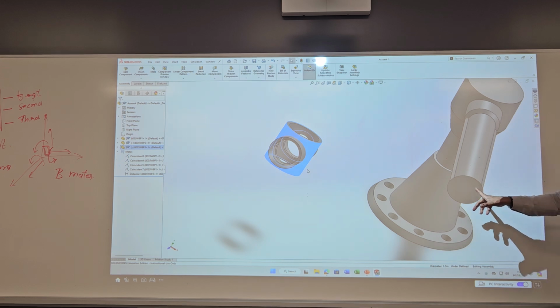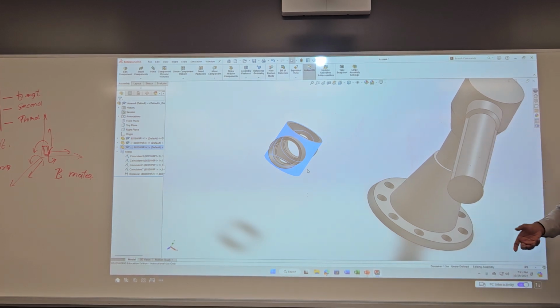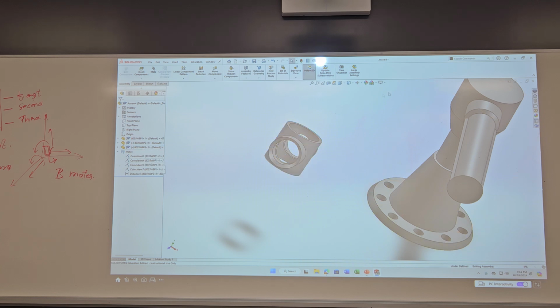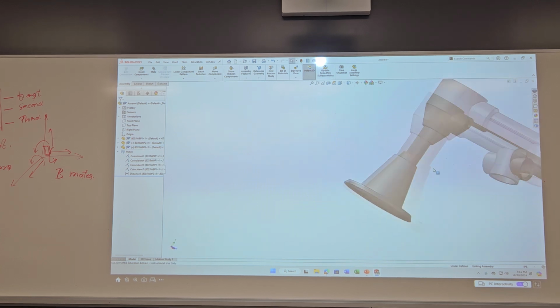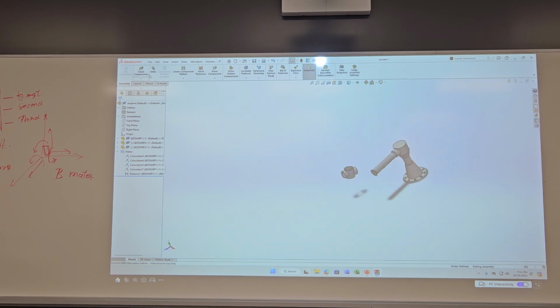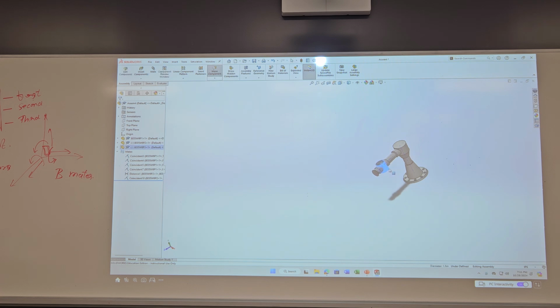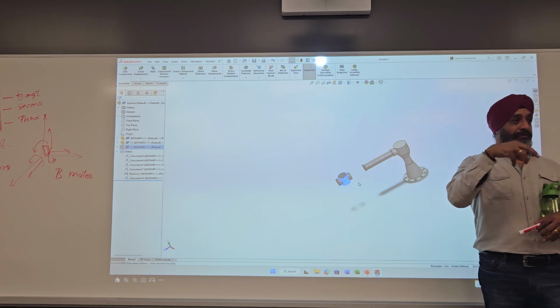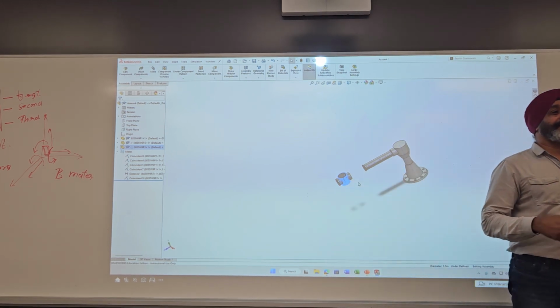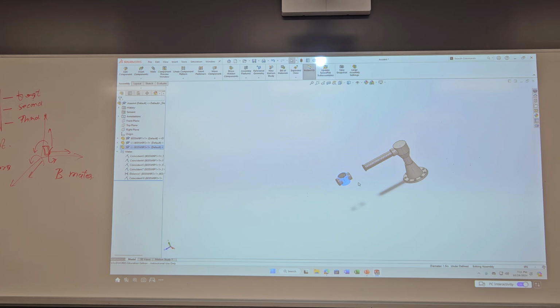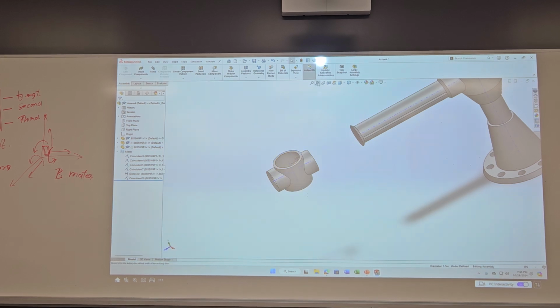So the first thing we can say is it is coaxial, because it still has to move center to center. Let's again visualize the temporary axis. So make this axis to this axis. I can move it in and out, but I can also rotate it. But the design intent is that it will not rotate, because those two little tapered bars on both sides and the groove in this part tell me that. So what do you think we should be doing? How do we stop that from happening?